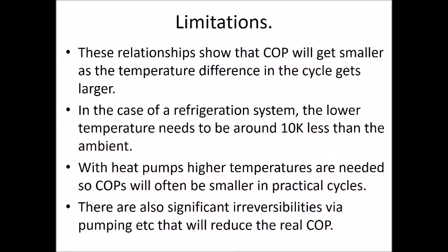But this is a reverse cycle. So to maximize our efficiency, we minimize the temperature difference, which is a stupid idea. And I guess this is where the really interesting part of this is. So to maximize the COP, we have to minimize the temperature difference. So I would now go to my client if I'm designing this and say, you wanted the best COP? Okay, here's the fridge. I've set it up for the best COP, and the temperature inside is 1 degree cooler than the temperature outside. And let's imagine it's a warm day and it's 25 degrees. The temperature inside my fridge is now 24 degrees. So your customer is going to say, this is not fit for purpose.